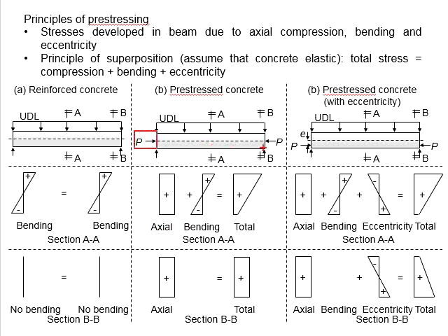Assuming that the compressive stress is equally distributed throughout the cross-section of the beam, the axial stress will look something like this. Then there will be bending caused by the UDL, which will give you tension at the beam soffit and compression on top of the beam. That gives you a bending stress, something like this.